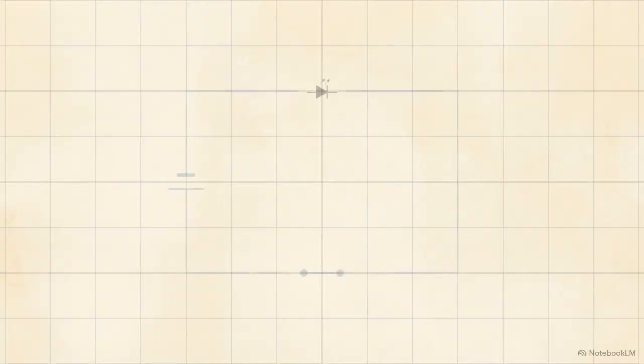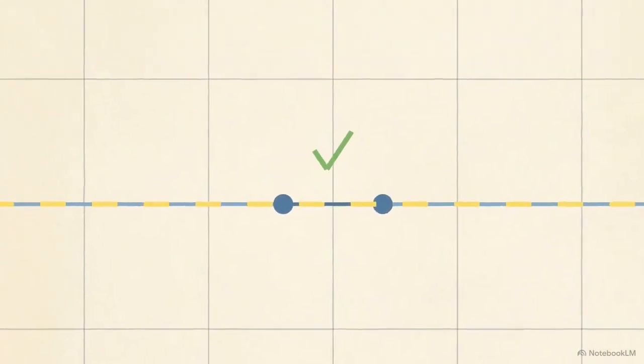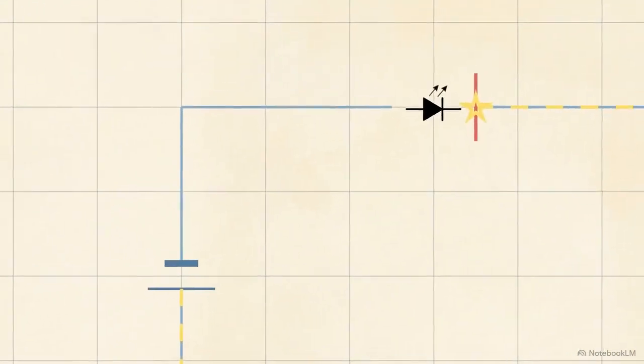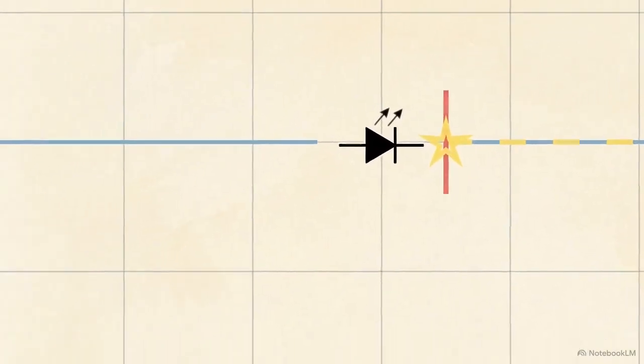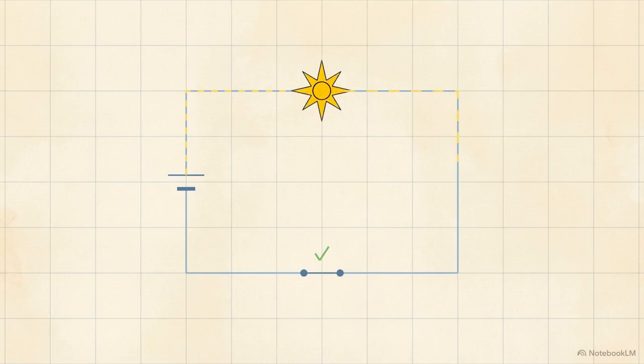Using this schematic, we diagnose the flashlight. Current is visibly blocked. The switch is closed, so it functions. However, the cell's long line pushes current against the flat wall of the LED triangle. Flipping the cell aligns the polarity, allowing current to flow.